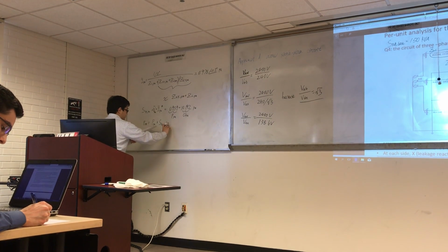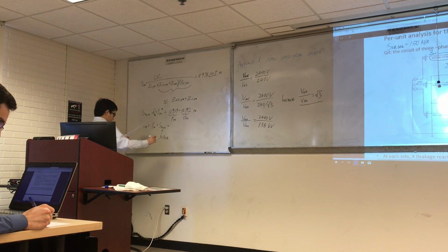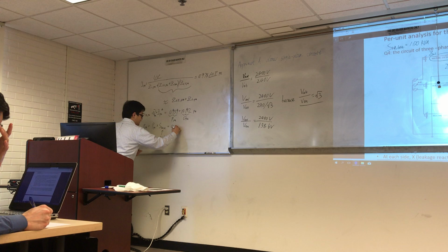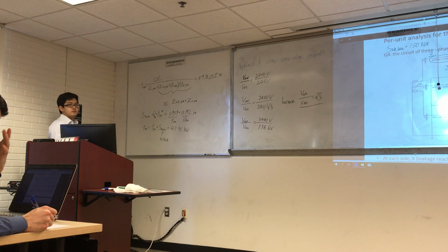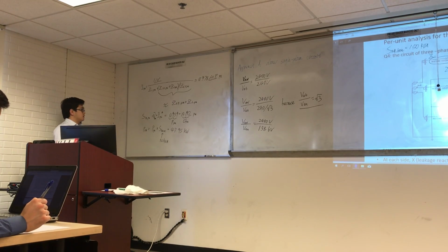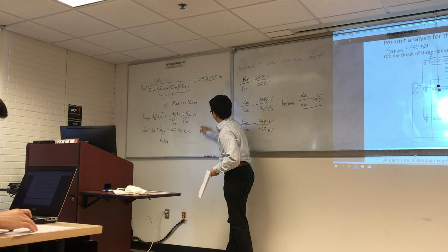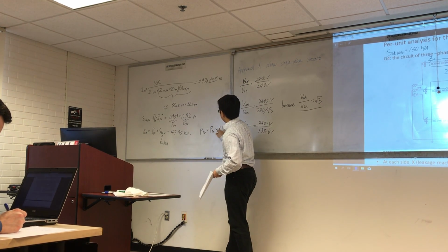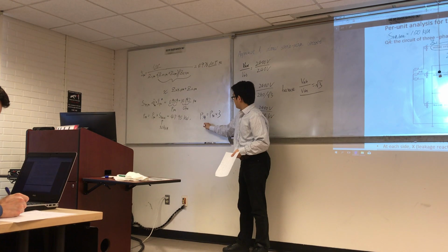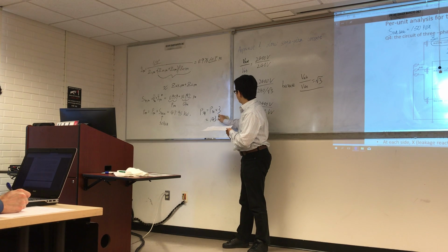So this is a 50 kVA. So this value is 47.95 kilowatt. This is a single phase. So for the three phase, P3 equals P times 3. Then your value is 143.85 kilowatt.